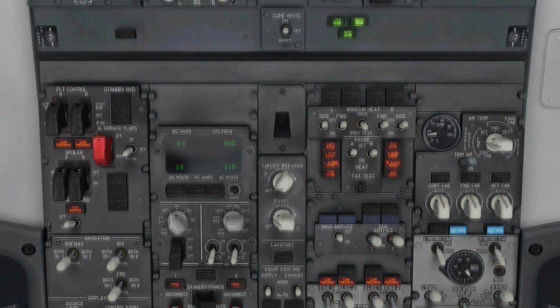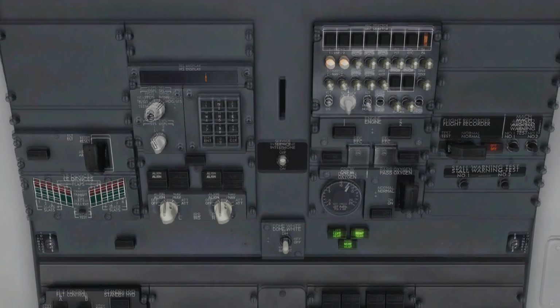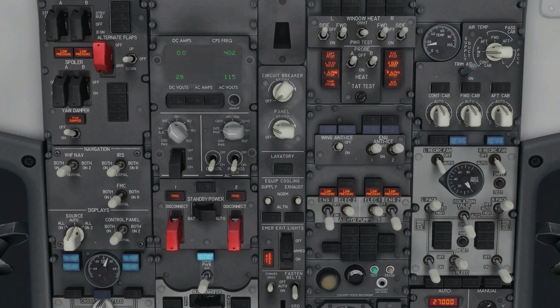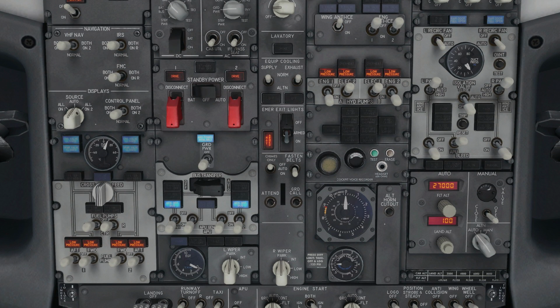Next we go up to the IRS. We'll switch that all the way over to the right for heading/sys. And we're going to basically click a line on both of them, and then once they go, the light goes out for the 1 minute, then we'll turn to nav, go into the FMC and set up the IRS. After that we've got cab, util and IFE, which is both on. We have emergency exit lights, which we can turn on right now. That's check.